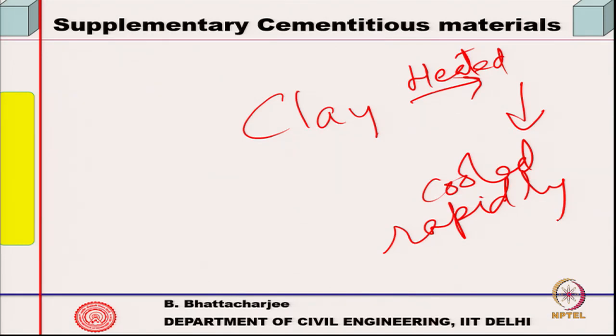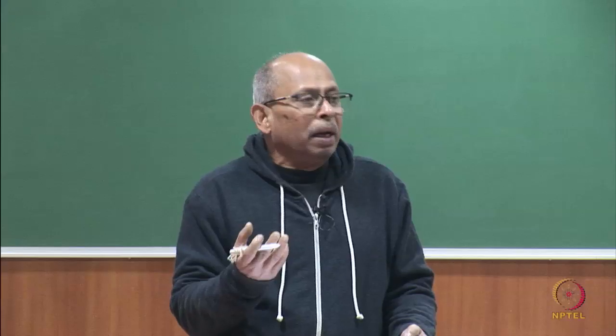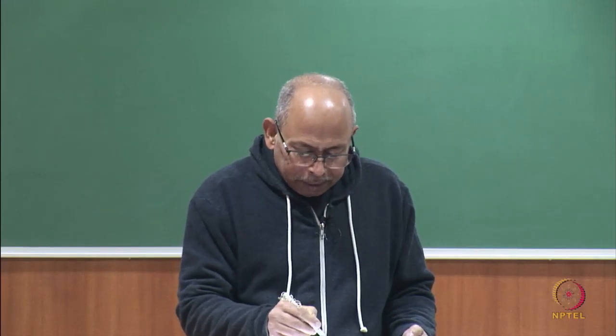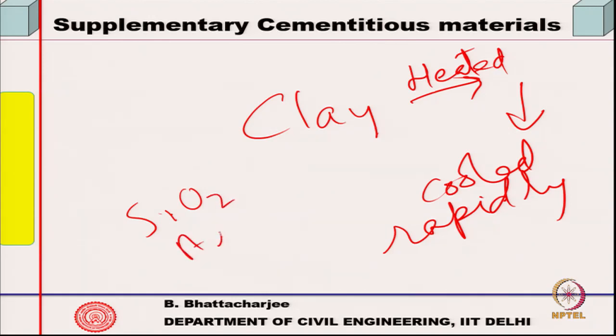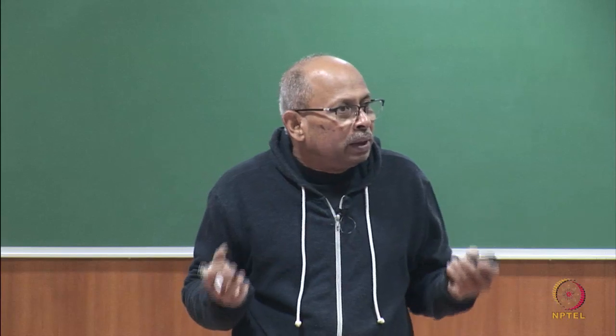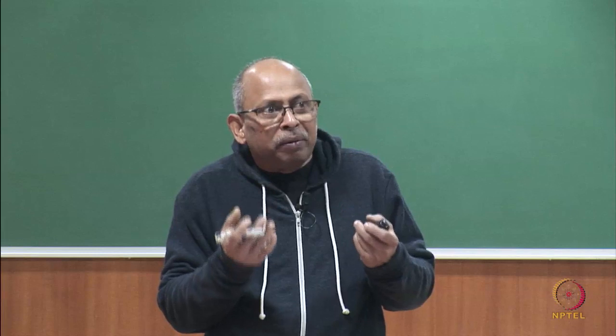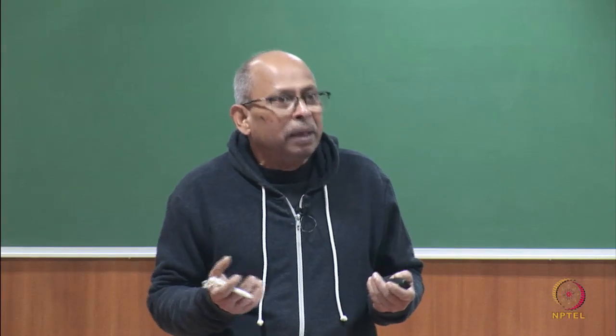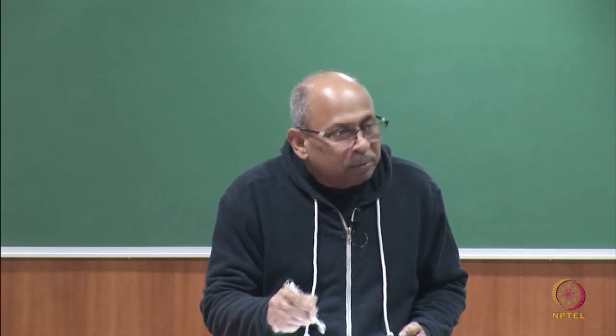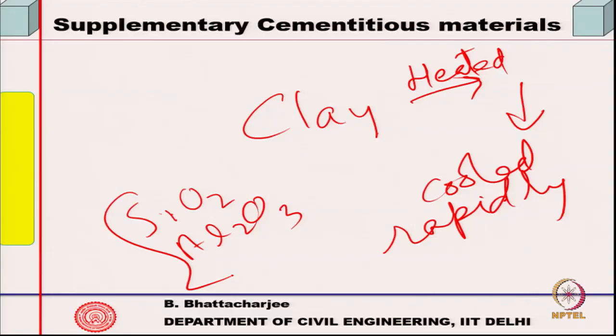Volcanic eruption. So, that clay again, because you have heated up the silica and alumina system and cooled it rapidly, that means a certain amount of energy would be trapped in it. It will not dissipate all the energy which has gone in heating, and therefore, its chemical potential is increased. It will have a reacting tendency. So, that would give rise to a reactive silica and alumina system.